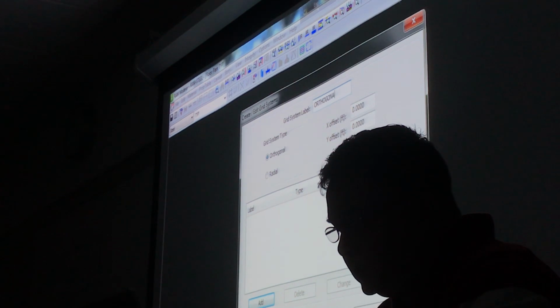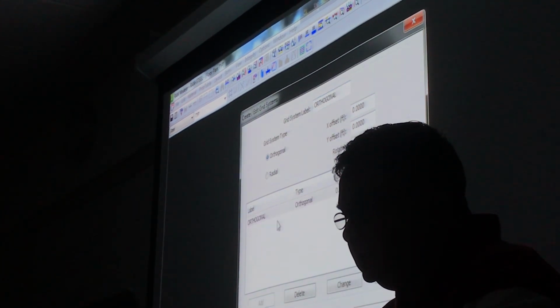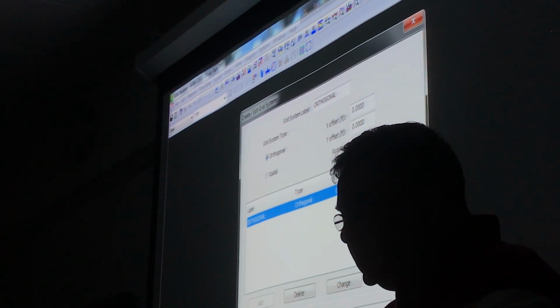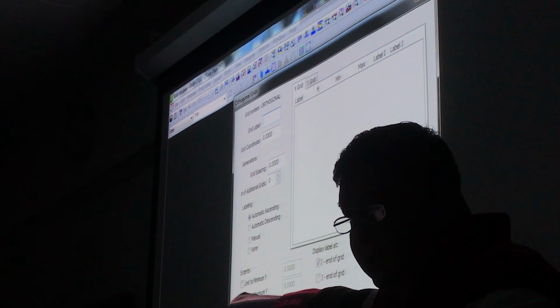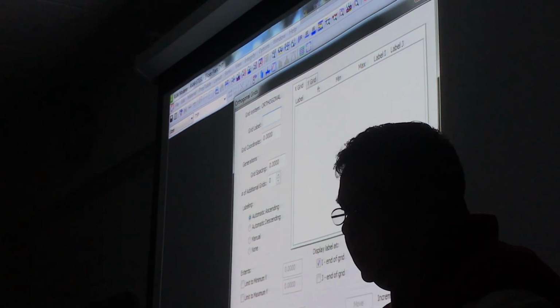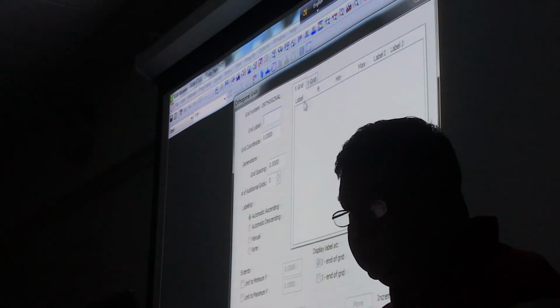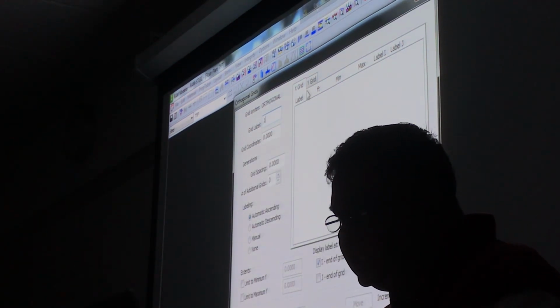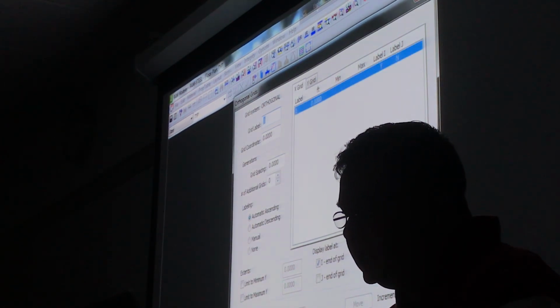Orthogonal means like perpendicular. And I'm going to add, and then select, and then edit grids, which is basically what we are going to do, like 1, 2, 3, A, B, C, D. So the first grid in the X grid means the ones that are vertical, okay? And the first grid is 1, grid coordinate is geometry, coordinate is 0, and I'm going to add them.